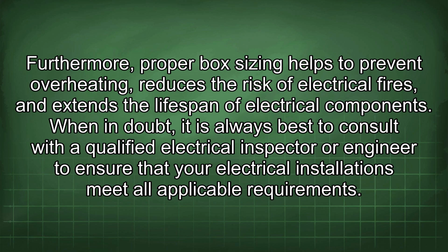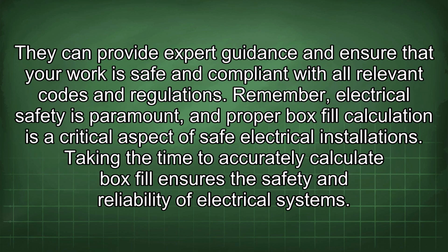Furthermore, proper box sizing helps to prevent overheating, reduces the risk of electrical fires, and extends the lifespan of electrical components. When in doubt, it is always best to consult with a qualified electrical inspector or engineer to ensure that your electrical installations meet all applicable requirements. They can provide expert guidance and ensure that your work is safe and compliant with all relevant codes and regulations. Remember, electrical safety is paramount, and proper box fill calculation is a critical aspect of safe electrical installations.